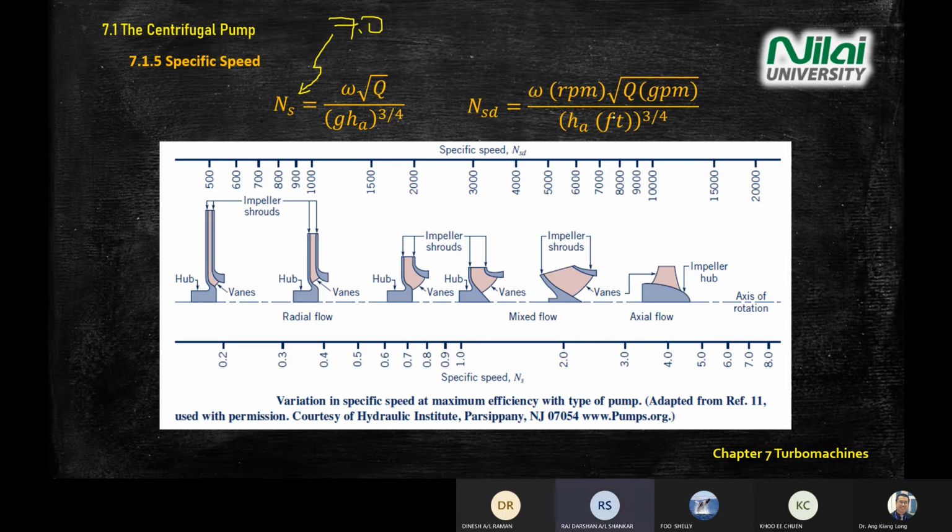So axial flow, sir. Correct. The answer is axial flow. You move up from 7.0 and it falls under axial flow. All right, so it's under here, axial flow. And if you need to communicate with your counterparts or colleagues in the United States, from this table you read up and there's a value there. It's around 18,000, the value for the specific speed.